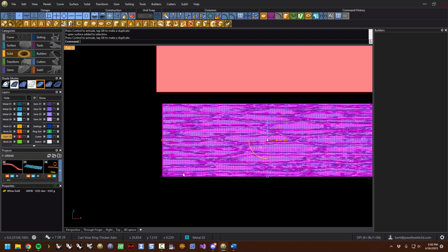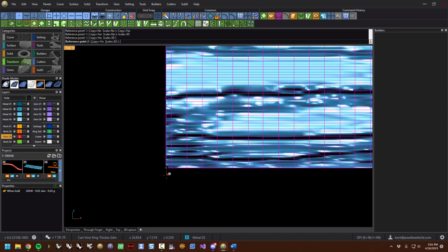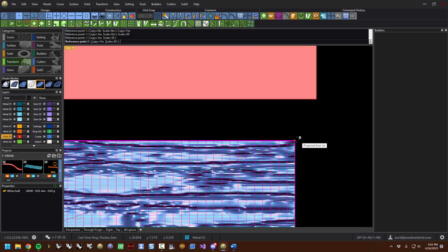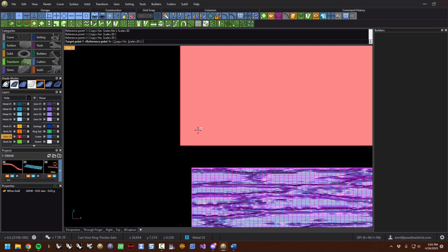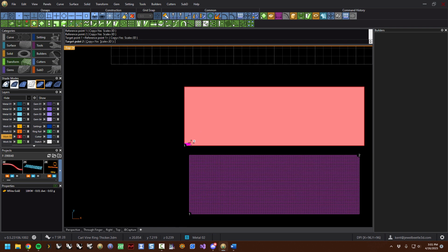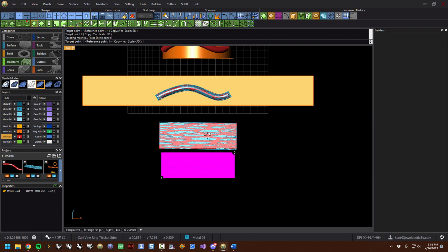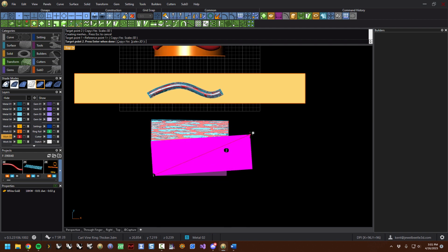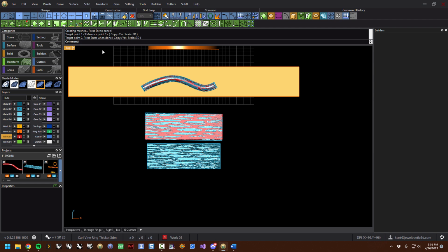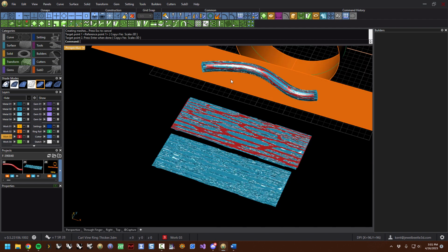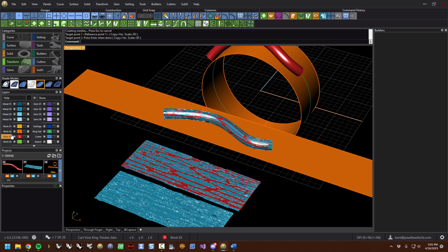We'll say, okay, I've got project on. We'll go to transform and go to orient to. Copy equals yes or no, it doesn't matter, we can have a copy. So I'm going to pick right on this corner, and then pick on the opposite corner, and then I'm going to translate that to this corner and that corner. So now that is up there. Okay, we'll hit enter, and we're done.